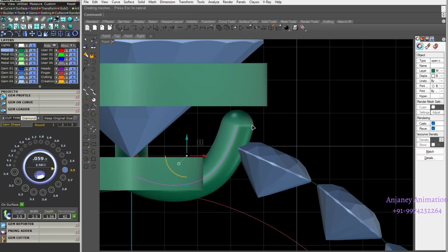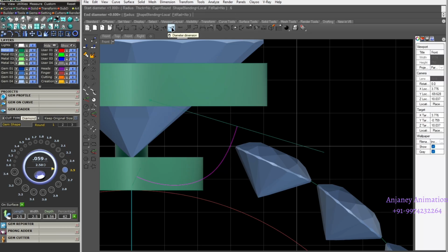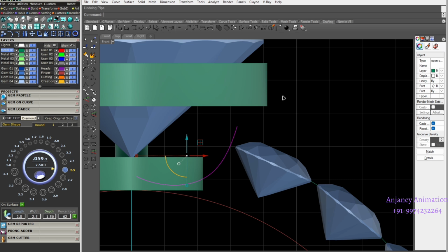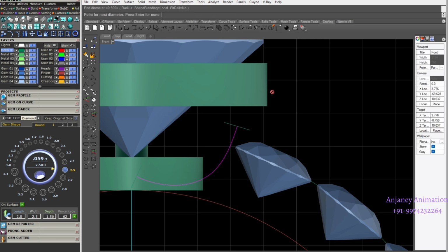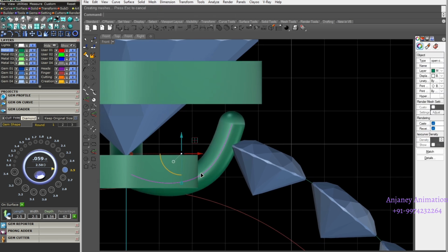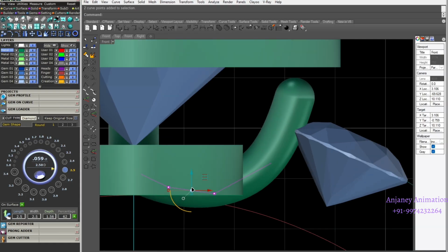Okay, now let's apply the pipe tool. After applying the pipe tool, you will be able to adjust the curve because you need to set the up and down position. So the pipe tool is a very ready-made option for a round cross section, meaning sections like a pipe.